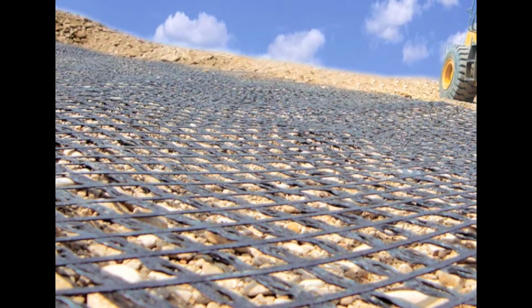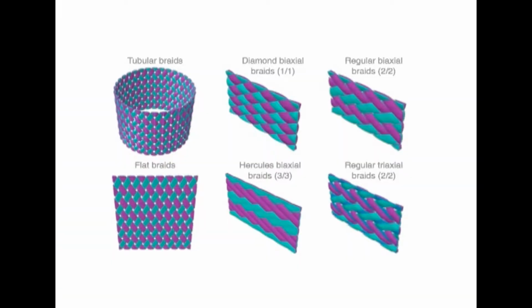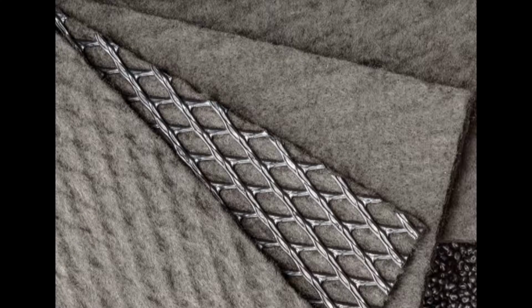These technical textiles are permeable fabric or synthetic material, woven or non-woven, which provides various unique properties such as good strength, separation or confinement, filtration, drainage, durability, reinforcement, low moisture absorption, thickness and protection. The major geo products are geogrids, geocomposites, geonets and geomembranes.